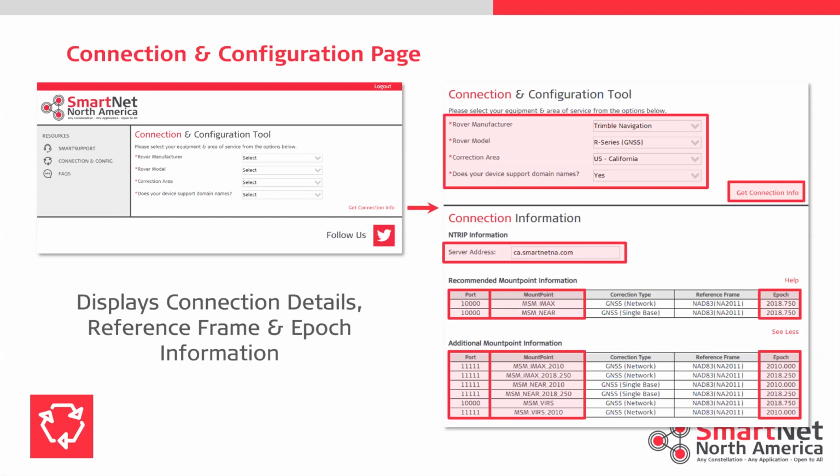Okay, so I know it's a lot of information. The short and skinny of it is, if you don't change anything, you're going to be moved to the new broadcast coordinates. It may or may not affect you depending on the station that you're connecting to and how much the coordinates get updated, but you need to be aware of it. And should you need to get back to the old solution, you can use one of the MRF mount points that allow you to use the coordinates that are operating today, the coordinates that you're accustomed to working with for the broadcast solution, and you'll have those available to you until the spring adjustment.